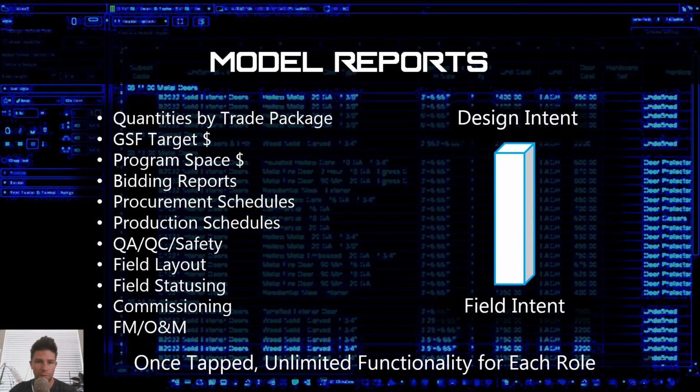So this is something that really excites me about ArchiCAD and this kind of untapped potential that we can really start getting into. So Graphisoft's done a really great job in these last few releases, starting with adding properties and then adding classifications, and now in version 22 adding expressions. It's going to take all those properties and really supercharge them for automating the data that populates those fields, so that it's less reliant on the end users to plug that information in. We can start setting up these expressions to really generate information that's more robust and more accurate.